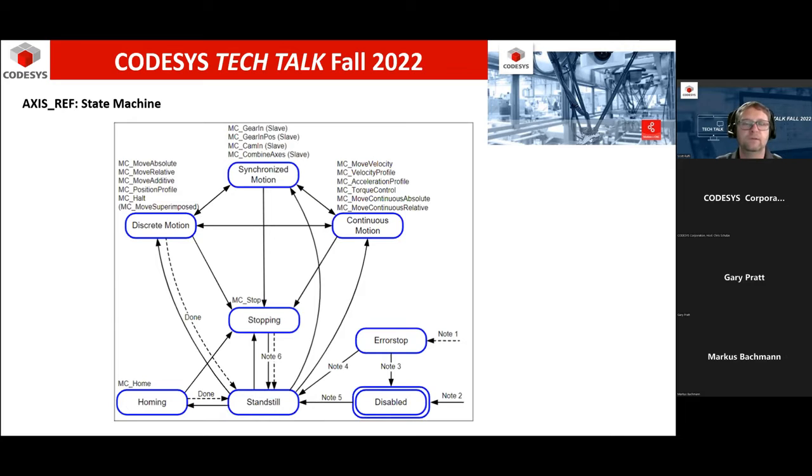This is just to give you an idea of the actual state machine and how the function blocks execute, in which order. This has been very valuable, not only here, but also with regard to PAC-ML, if you're familiar with that at all. It's very nice to be able to see this and understand what state the machine's in, and when you're programming, to jump into a state, come out of a state, and know which one you're in.